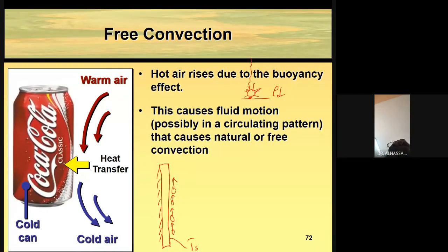So then again, those fluids that have high density, which are very far away from the hot plate, will be moving down like this. And then the low density fluid will be moving upwards like this. So we will have a situation like this where these are low density fluids. Now, because there is no hot surface that continues in this region, the fluid will be forced to divert itself in this direction. So gradually, its temperature will become equal to the ambient temperature.